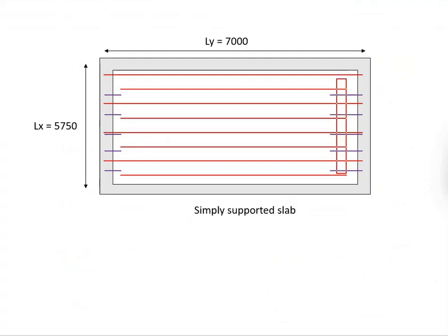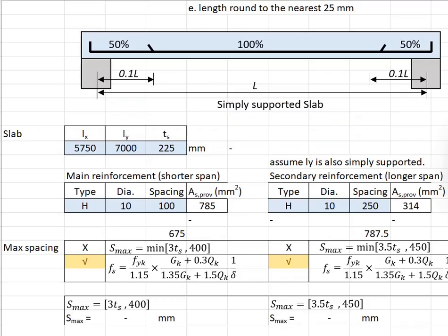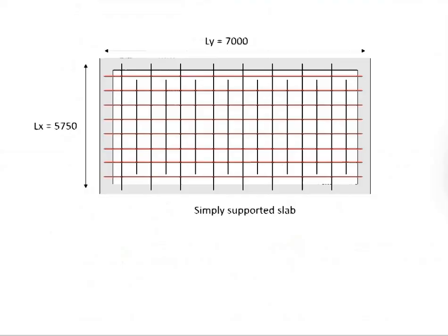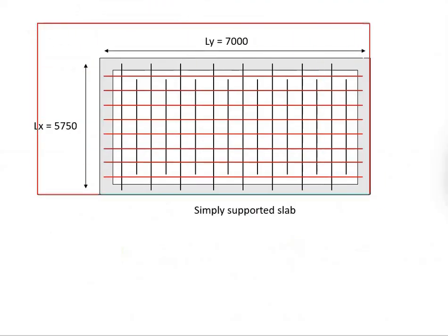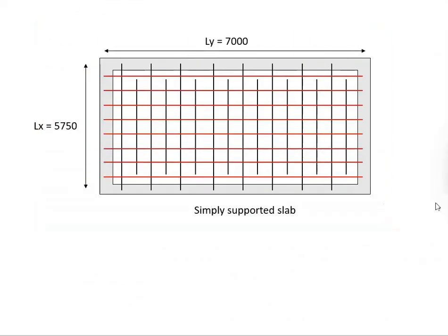This is the third situation leading to you, in practice, having the curtailment of the reinforcement bar at a spacing inconsistent with the midspan reinforcement bar spacing. Because of these 1 through 3 situations, you might as well not do any curtailment, leading to the final layout of the reinforcement something like this. Simpler to construct and easier to monitor.